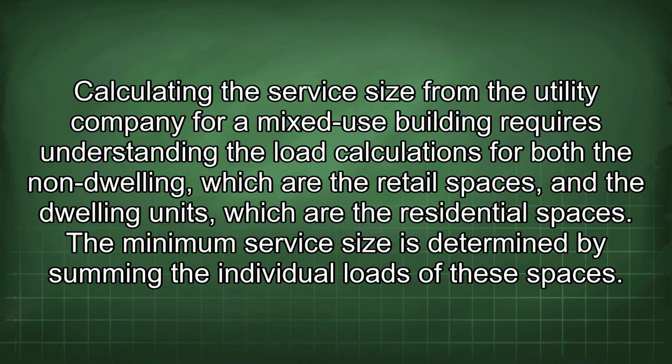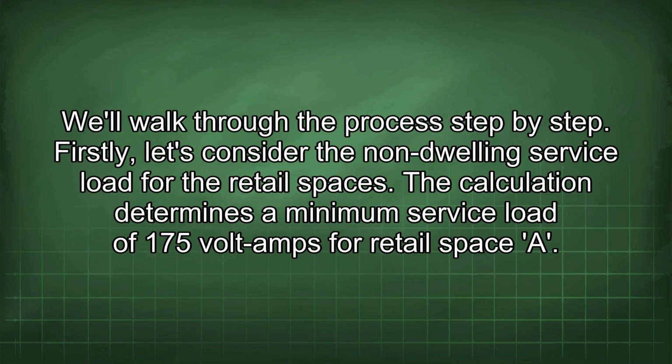Calculating the service size from the utility company for a mixed-use building requires understanding the load calculations for both the non-dwelling, which are the retail spaces, and the dwelling units, which are the residential spaces. The minimum service size is determined by summing the individual loads of these spaces. We'll walk through the process step by step.